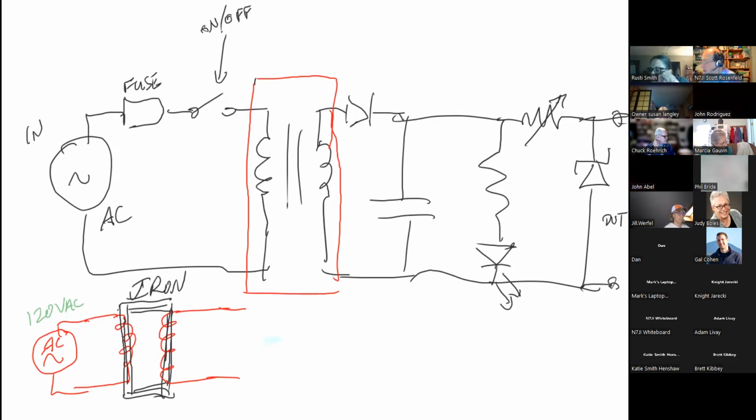Well, that means you don't need all that voltage, so what you would have is a step-down transformer. Where else would you find a step-down transformer? And I'll give you a hint. The voltage that it's stepping down from is 12,700 volts. Transmission lines. You look out on your power pole the next time you go outside. Look at the transformer that's feeding your house. You'll have a 12,700 volt transmission line, or sometimes higher, feeding it, and you have a nice clean 120 volts AC coming out of the other side. That would be a step-down transformer.